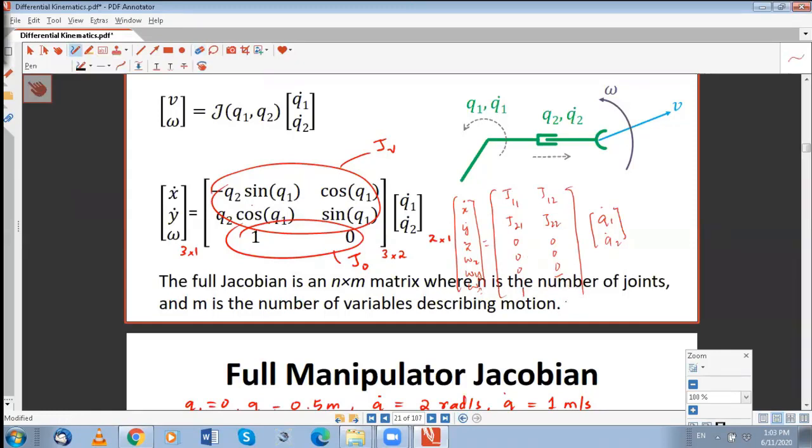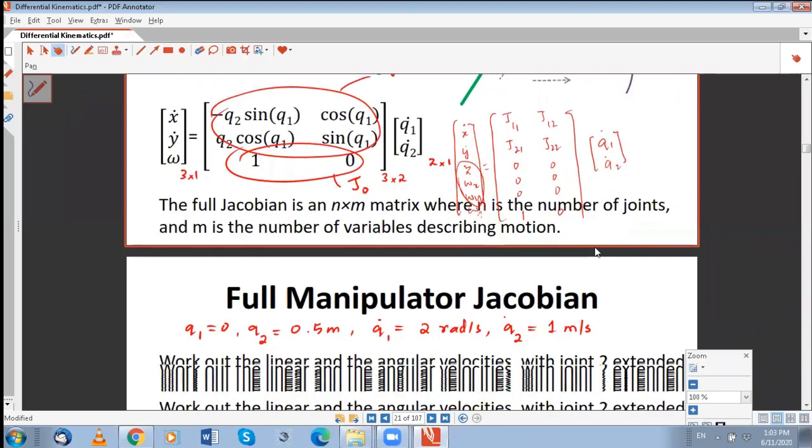But the reason I'm not writing the Jacobian like this is I know that because of the geometry of the arm, this motion is never possible. So why write it in the velocity vector? We just write 3 velocities, we don't write 6. You can write 6 velocities, but you would have those 3 zero rows, which doesn't make any sense. But if you have, let's say, 6 joints here, these elements will also be non-zero. So generally the Jacobian is 6 by n. Okay, n here is 2.